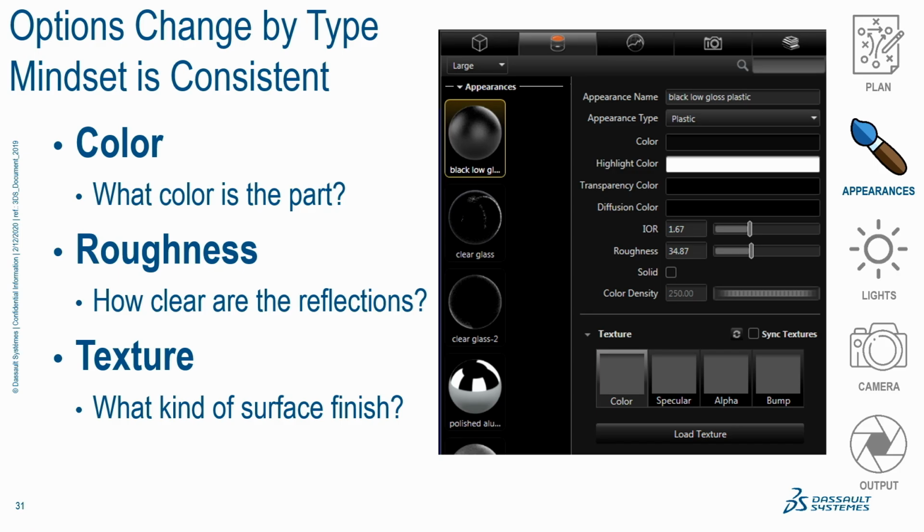So you can have your company website open on one monitor and your Visualize open on the other. You can choose a color, hit the little pipette, and you can color reference from your company's website. So you have pretty good flexibility as far as where those colors are coming from, obviously RGB values or whatever else you want to use. But you can mess with those in pretty much every appearance.